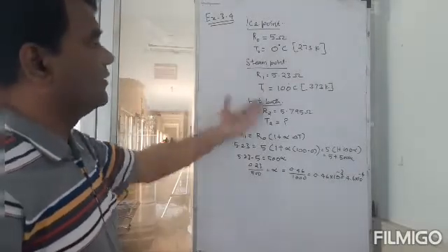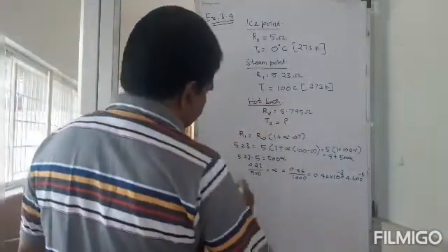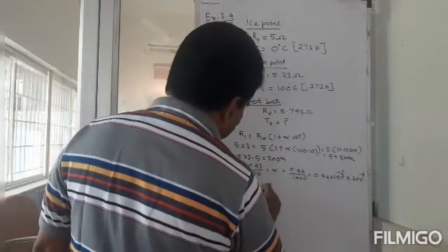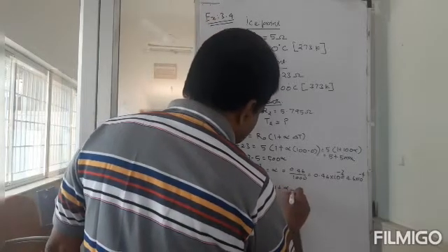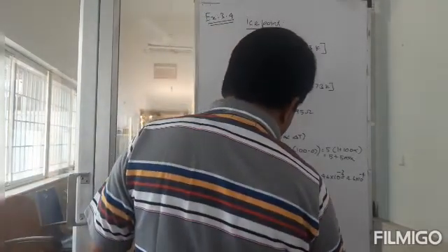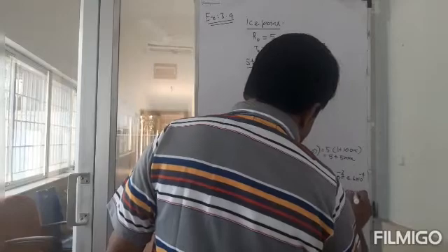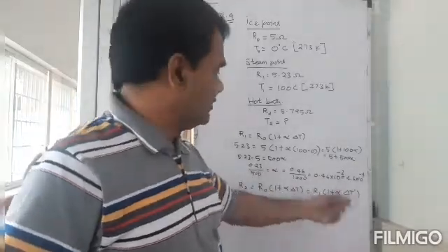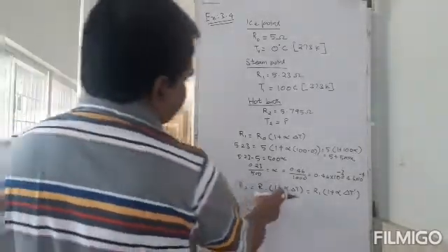Now I can use this alpha in the other equation. I can use this or that. Anything can be used. Next one, R2. Because it's all linear, then I can make use of this expression. What is R2? R2 can be written as R0 into 1 plus alpha delta T. It can also be written as R1 into 1 plus alpha into maybe delta T, something else, okay? Because I'm not going to get the same delta T, it will be different. That's why I'm putting delta T dash. Otherwise, either should work, okay? So it doesn't matter. I want to take the first one, this one.